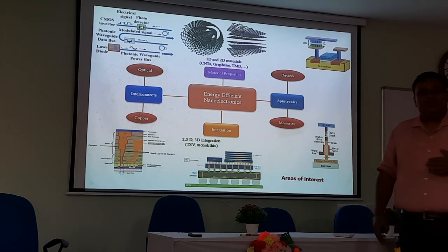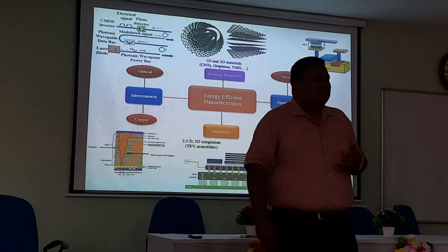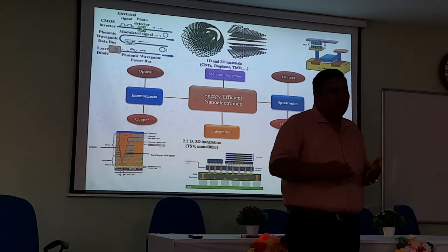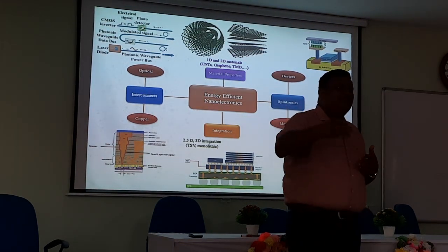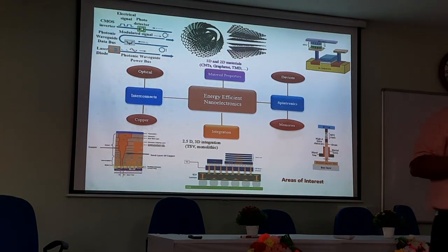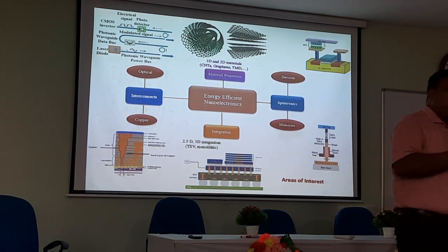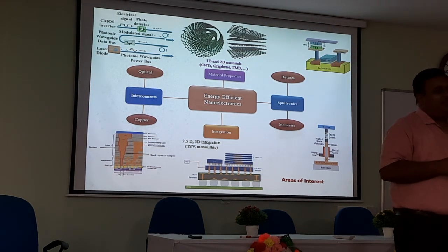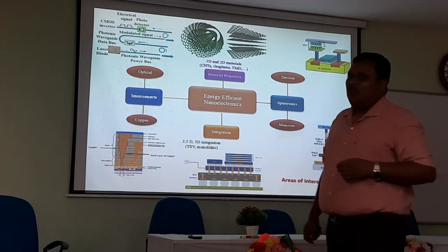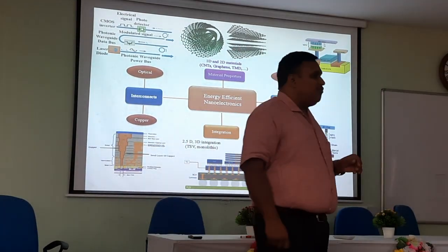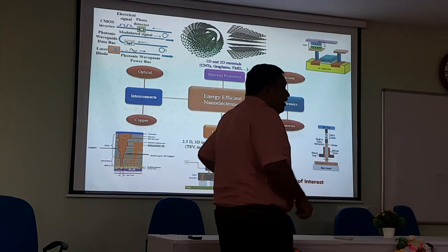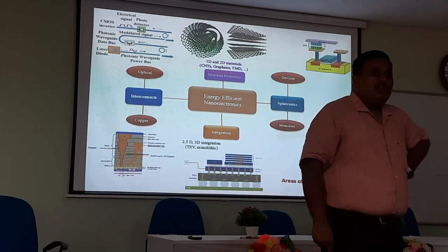But when we did all the analysis, we realized that spin would probably be good enough only for shorter lengths. As the interconnect length increases, it won't be really good because spin has its own relaxation time. It will be there for some time, and then as it moves on, it will lose its spin. Therefore, it was not good for global interconnects, and most of the research across the world was being done only for global interconnects. But during that time, we realized that yes, spintronics is really good for memories.